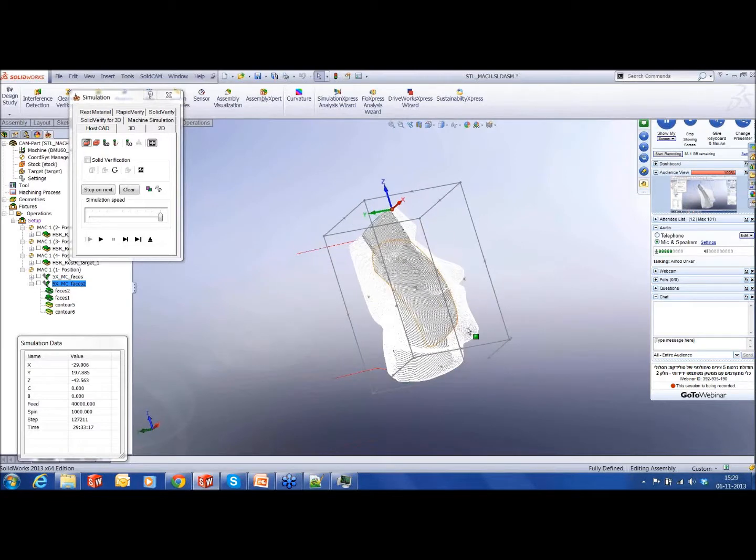So it's actually going to rotate the entire table to keep continuously machining this particular STL face geometry that you have seen on 5-axis. So using these principles of projection available in SolidCAM 5-axis simultaneous, you can cut any kind of STL geometry. It doesn't matter from where the sources come. As long as you have the STL geometry, you can create those guiding surfaces and cut the part straight away.